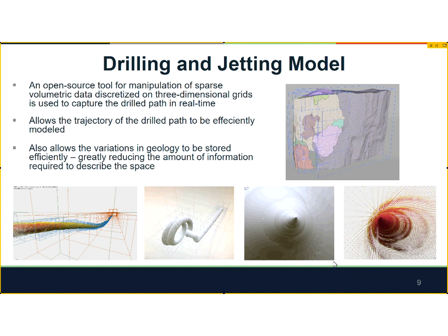Then we can take these points, and it has a function to create a level set, and we create basically a 3D model. This is in turn part of the boundary condition that's passed into the Drillstring model for computing the friction of the entire Drillstring for the history of the drilled hole, so that we can look at how tortuous this hole is and see what force it would take to pull a pipe through that, or if the pipe would fail long before you ever had any chance of sliding something through that system.